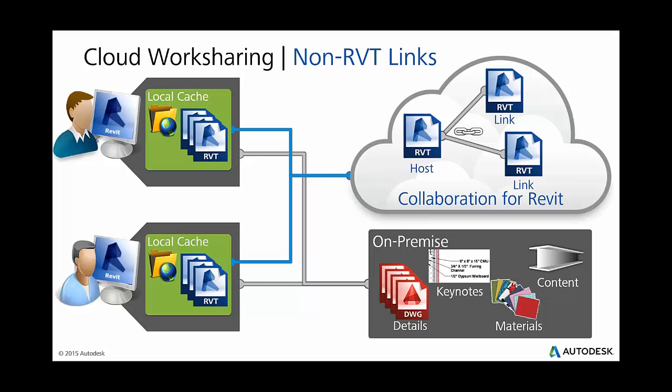Because Revit, by design, and for 8 years now, transacts in deltas, it's not very common that Sync with Central is going to be pushing a huge amount of data. Usually it's on the order of 5 to 10 megabytes for Sync with Central, even if you're dealing with a model that's 600 megabytes. So that's kind of Revit's architecture today. But yeah, if you pull the cord or you lose your connection, it's going to cancel the transaction. And if you get a good connection again, you can go ahead and try it again.